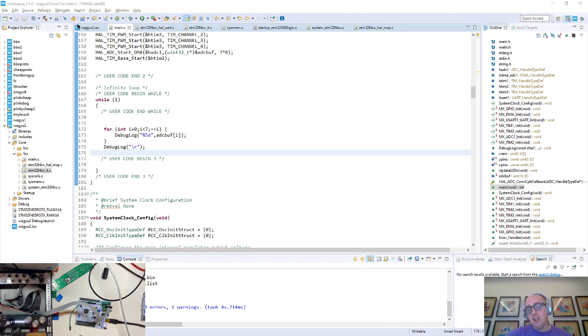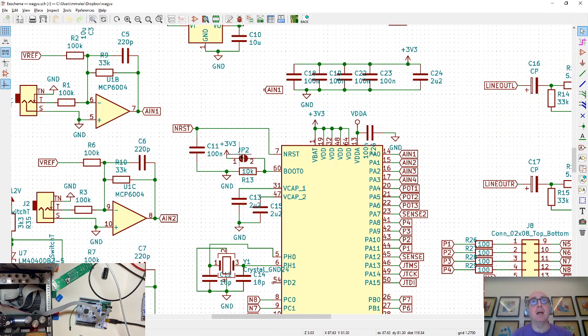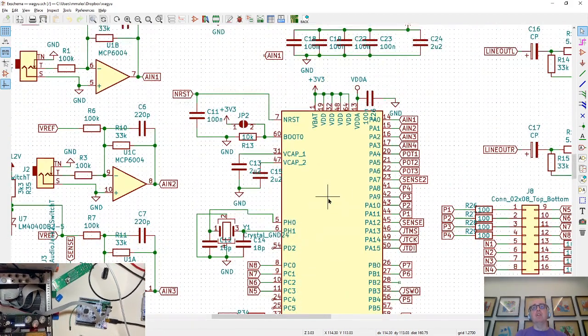And then just basically you muck around in the CubeIDE like I'm doing today, and then your pins just work. And what I love about it is that the transition to a PCB is then so simple because the chip basically needs a bunch of capacitors to decouple it and a reset button, and well, that's it. As you've seen in the schematic, this jumper is a panic jumper, which you probably don't have to use. This is the boot. Well, that's part of the panic switch. This is the reset capacitor. These are the stabilization capacitors, a crystal, and then everything else could just be on headers, a couple of caps. So yeah, that's what I love about it.